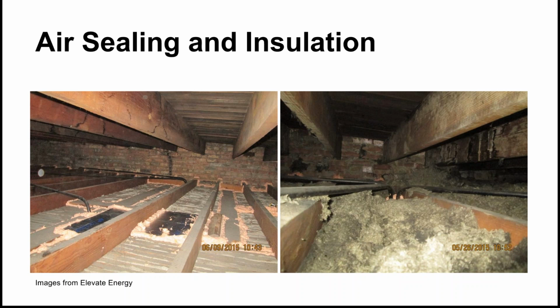So when you're looking at sealing a building, you have to focus on how to fix both of these problems of air leakage, the holes and the pressure. And while you could go through the building and look at every single hole that could possibly be there, really what you should be doing is focusing on bigger leaks and leaks that are at points of high pressure, so in the basement and in the attic.